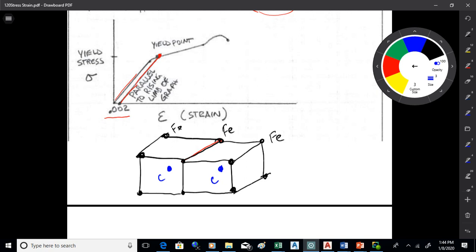Ductile and brittle. Yeah, I think what you do, you use a softer steel that isn't quite as strong, but it's ductile, and it's called ductile iron. And there's reasons for that. The first thing is, if you have a failure on a structure, you don't want to have a brittle fracturing failure like glass, like cast iron would fail, because it's sudden. You get no warning about it. There's no elongation, and it just shatters. You do not want that. What you want is more of a ductile failure, where things stretch. You have some appearance of failure before it occurs, so you get some warning it's going to occur. And also, by stretching, it absorbs energy too.